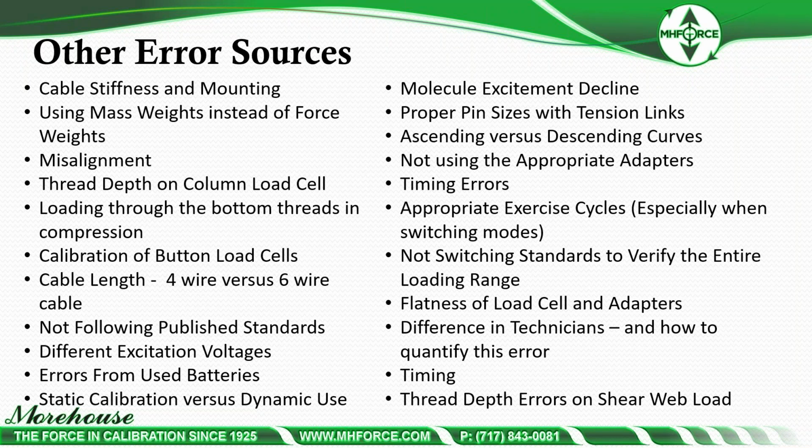Thread depth on a column load cell, loading through the bottom threads and compression, all these error sources, static calibrations versus dynamic use. There's a nice session that's going to be given by NIST on fundamentals of dynamic force metrology at NCSLI this year, 2018, August 29th in Portland, if anyone's going. That's session 5, and a very good presentation on dynamic force.